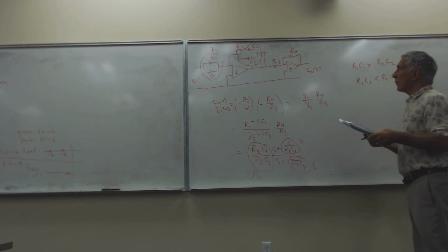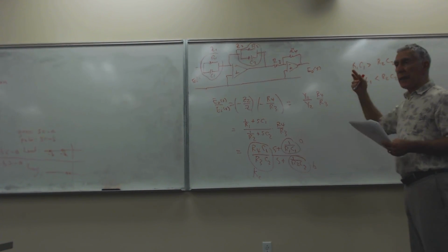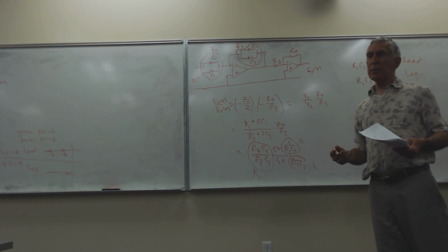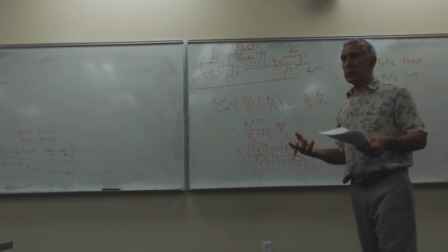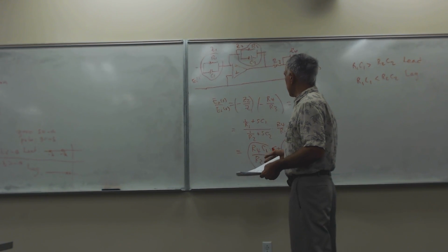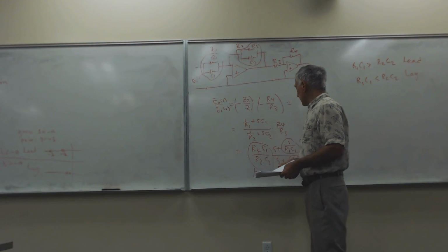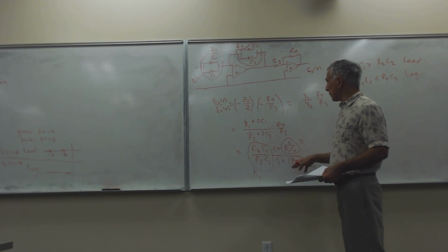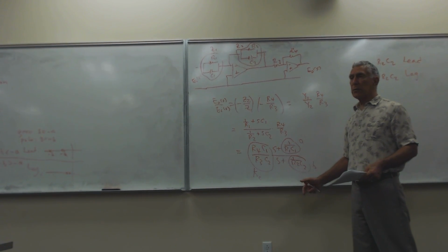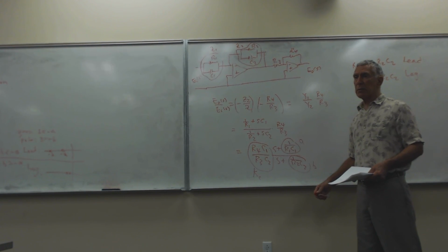So, this is the analog compensator. Right. These days it's not done with analog. It's done digitally. Once you know the values, you can convert this transfer function to a discrete time transfer function.